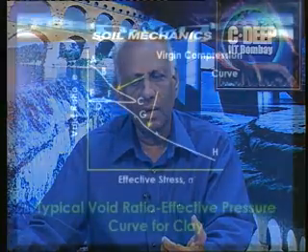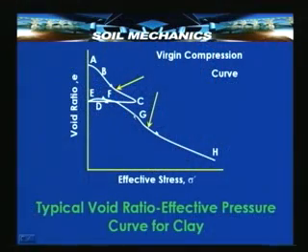Now, suppose you once again load, go from E, start applying the load, then we are actually recompressing the soil which had already been compressed once. Therefore, from E to F, the compression will gradually take place along a line which is almost parallel to this ABC and will reach a certain point G corresponding to the load which had been applied earlier.